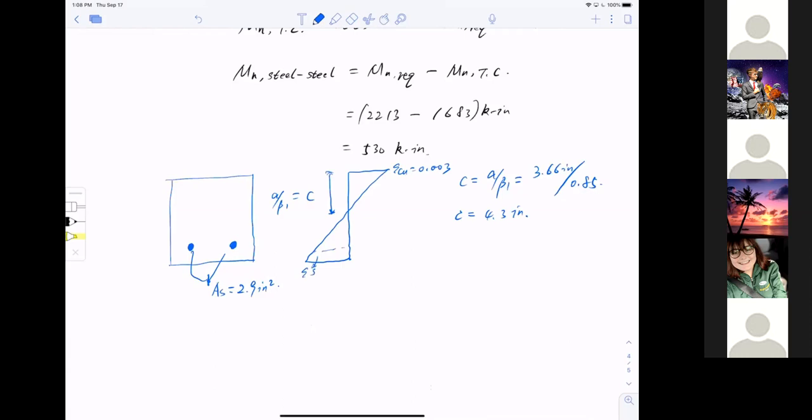Okay, that's my steel right there. Now, the problem we have is the design is inadequate. That means I need additional moment. So where can I find this additional moment? I'm just going to assume I'm going to put some bars here in the compressive zone. I don't know how much, but let's say AS prime.